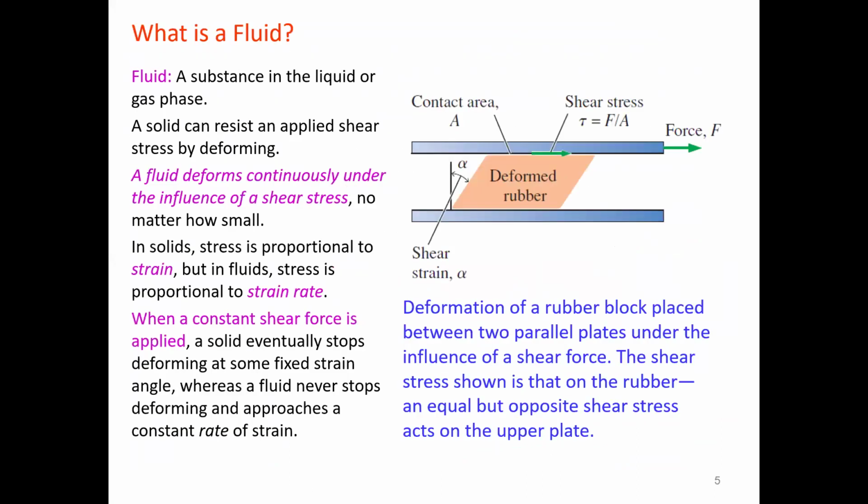Now, what do we mean by fluid? A substance which is capable of deforming continuously, we can call a fluid, or the combination of liquids and gases we can call a fluid. In another form, we can define a fluid as a substance which deforms continuously under the influence of a shear stress.